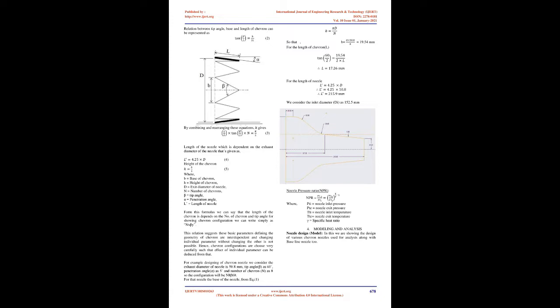Air was entering from tubes tangent to the nozzle outer surface at 3 different points along the chevron at the exit of the nozzle: near the chevron notch, at the chevron middle point, and near the chevron tip. 3 entering pressures were used for each injection tube location, 10, 30, and 50 psig, giving entering mass flow rates of 0.1, 0.2, and 0.3% of the nozzle total mass flow.